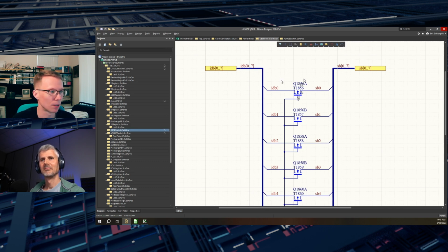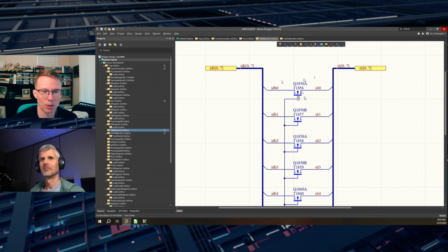And so these particular FETs are fairly small. They're designed to be used for differential pairs in analog amplifiers and stuff like that. And so their RDS on is fairly high, and the saturation current limit is also fairly low. I think these saturate around 8 milliamps or so. And so all of that acts as a speed limit, because when you're trying to drive the bus with all the bus capacitance, you can only do it so quickly.